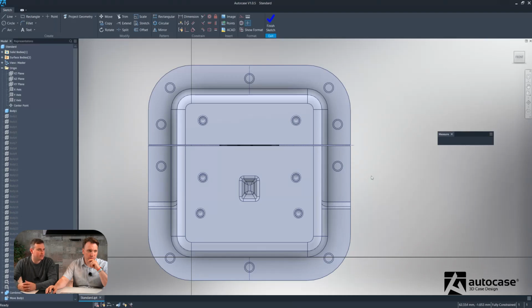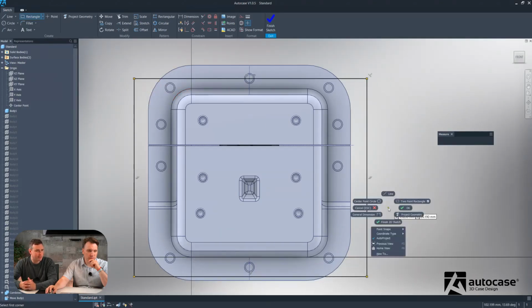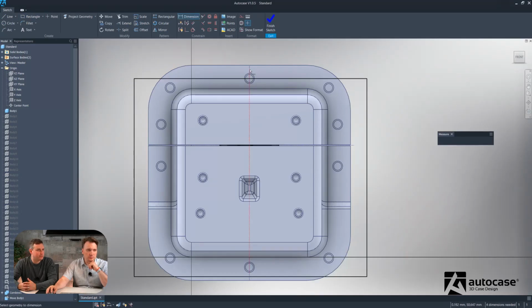So we'll first draw a large rectangle, which will then essentially confine and snap to these lines using measurements. So using the dimension tool, we're going to use that construction line and use the edge. Now we have a measurement that is currently reading the width of that part of the box. Same on the other side. So at this point, we'll link those two measurements together. Do that by simply clicking and then clicking again, then enter.